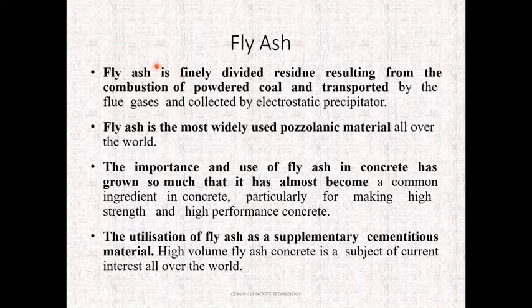Fly ash. Fly ash is finely divided residue resulting from the combustion of powdered coal, transported by flue gases and collected by an electrostatic precipitator. The fly ash is the most commonly used pozzolana all over the world. The importance and use of the fly ash in the concrete has grown so significant, particularly for making high strength and high performance concrete. Utilization of the fly ash as a supplementary cementitious material is a subject of current interest all over the world.